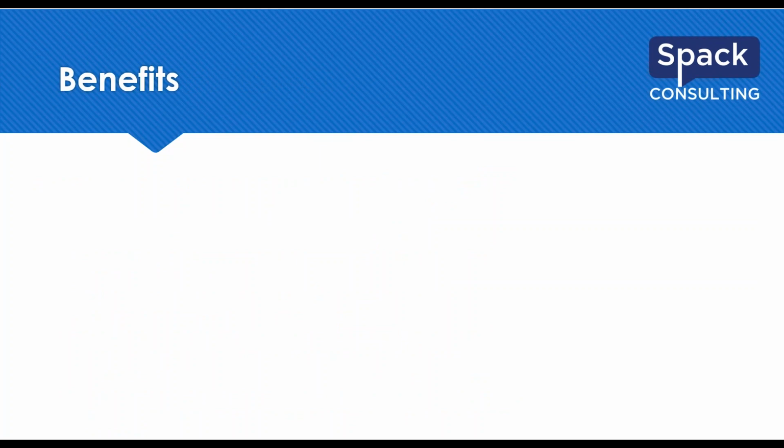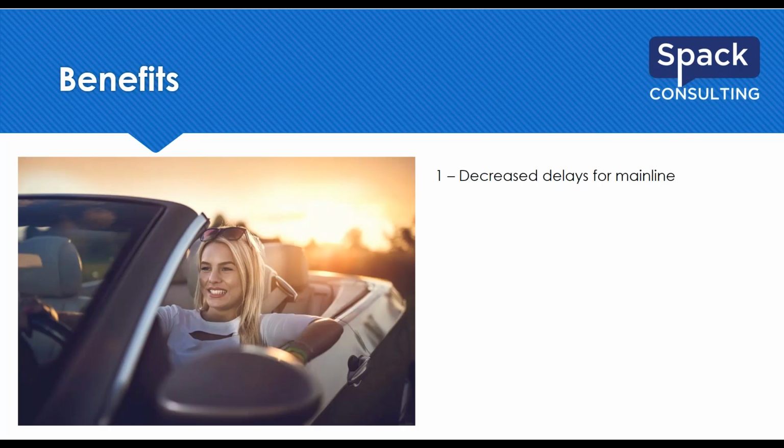So right along with that, as we think about the guidelines and the engineering judgment for taking it out, what could be some of the benefits? Why would you want to take that out? One of the main ones is you get some happy drivers, particularly on the main line. You get decreased delay instead of having to stop at a stoplight. Presumably, if you're going to a two-way stop or a roundabout or something, you might get those decreased delays. That could definitely be a nice benefit for a majority of the drivers.